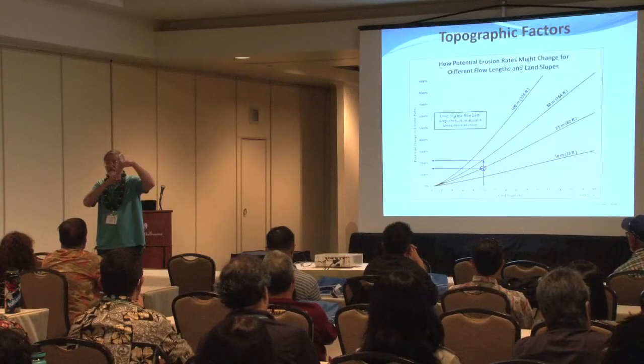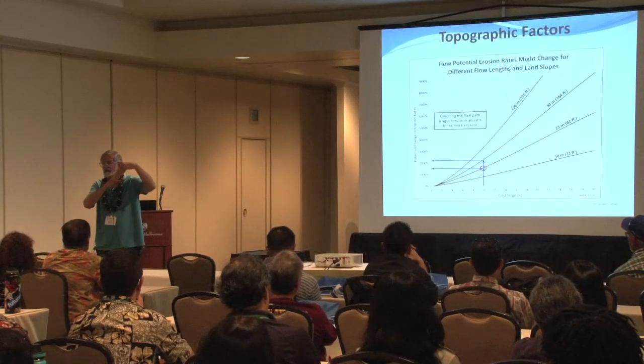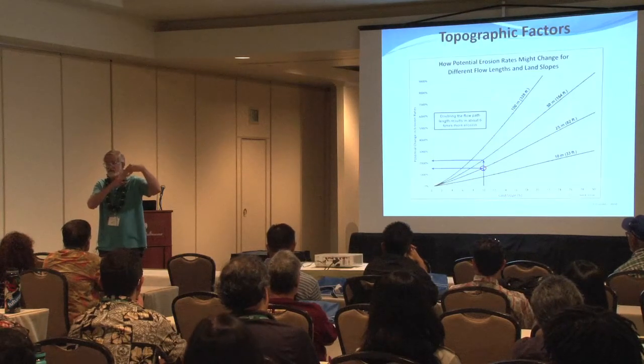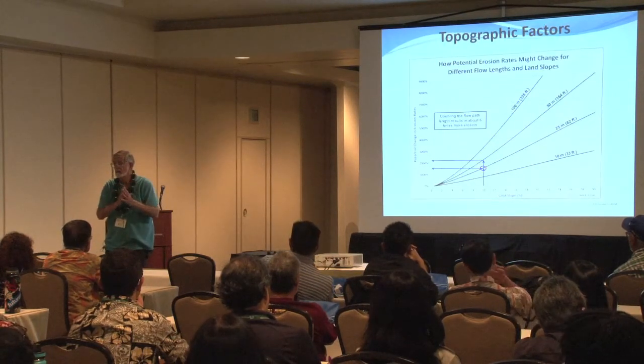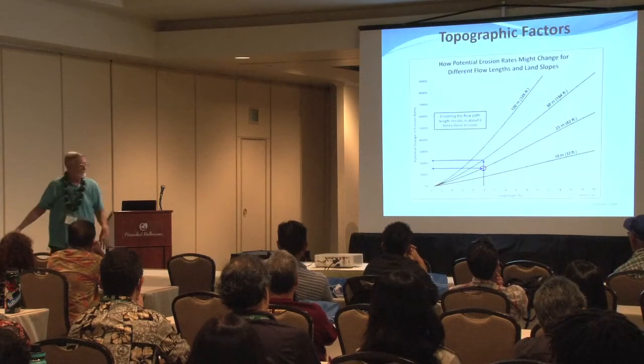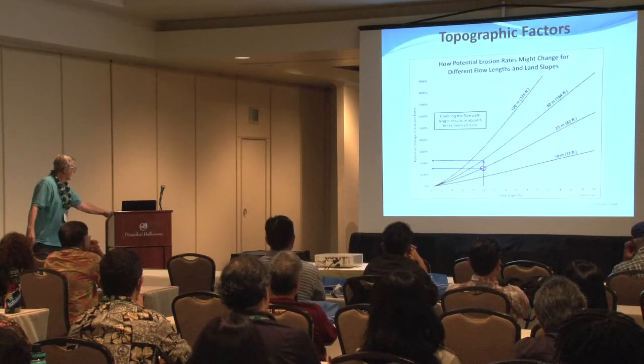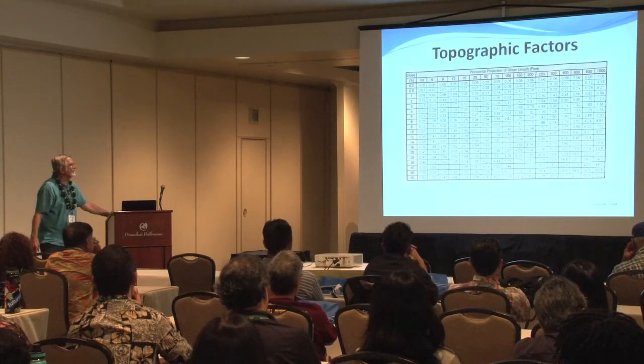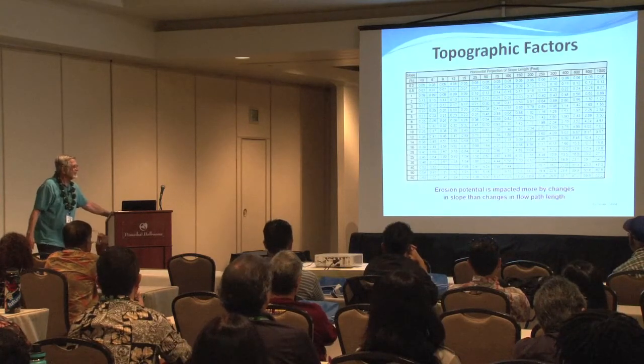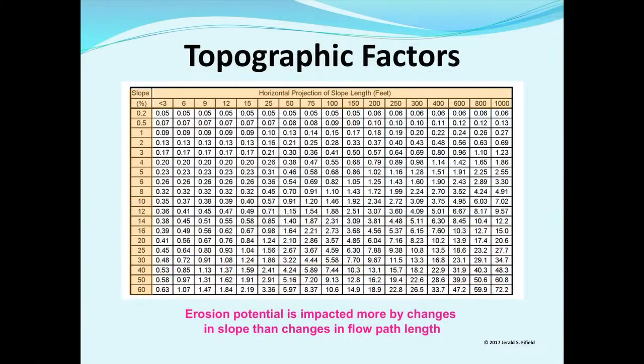But if you have slopes in there, and occasionally I understand that highway departments work on some steep lands around here, occasionally. So be careful with it. These are all part of the modeling aspect of it. So basically, remember, when you're dealing with erosion, you're modeling it, it's more impacted by slope than it is by how far water travels.